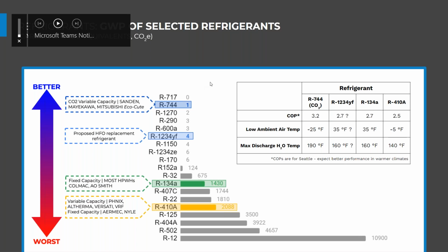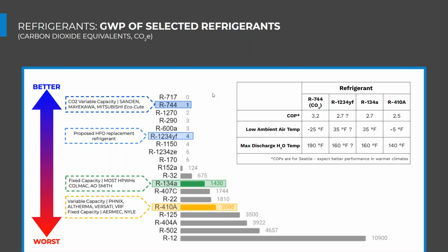All right, so global warming potential, it's important for our heat pump water heaters, but I would like to highlight that in these packaged commercial heat pump water heater products, we typically have a very low volume of this toxic refrigerant. So our VRF based conditioning systems, right? We have piping going through the entire building, carrying this refrigerant in it.